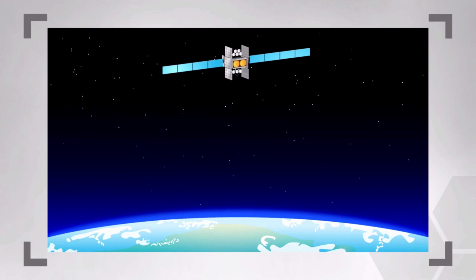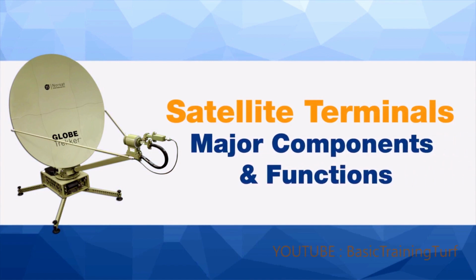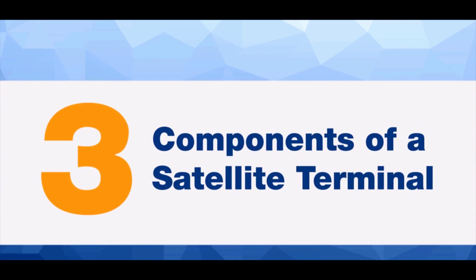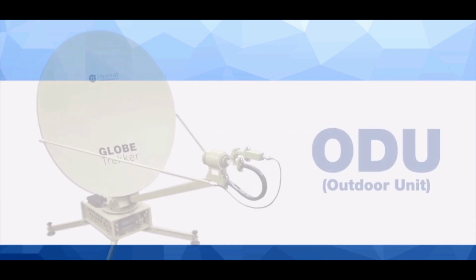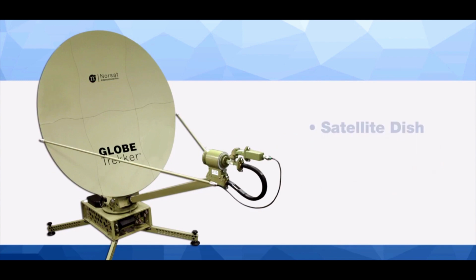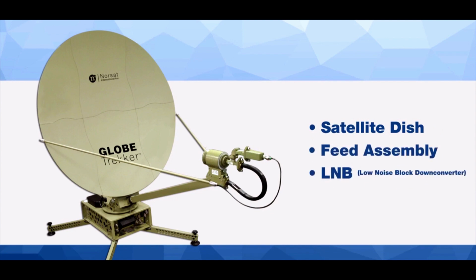Which now brings us to gaining a further insight into how SATCOM supported communications works. Satellite terminals and their major components and functions. Before we jump into the major components and functions, we should first talk about the three components of a satellite terminal subsystem. The ODU, or outdoor unit, refers to the set of antenna equipment that is placed outside of the building. The ODU typically includes a satellite dish, feed assembly, LNB, and block up converter.